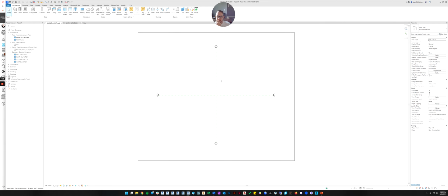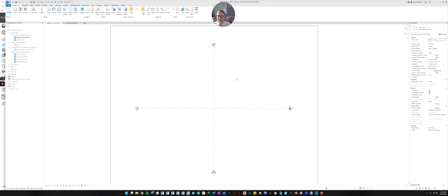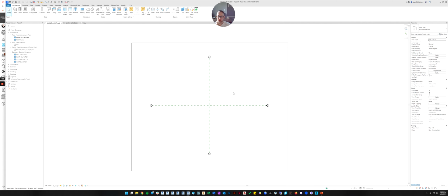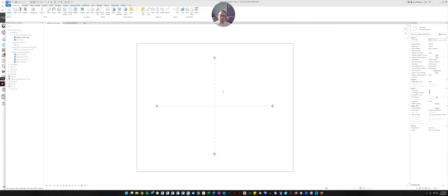So now let's talk about how we start modeling. You know how to model walls, floors, ceilings, roofs. That's great. You've got the fundamentals, but now if you're going to do it off of an existing floor plan, how's the best way to do that? So I'm going to show you how I do it. You could just open up the image file on your iPad or your phone, and you could look from there and try to start building it from there. But I like to bring the image into Revit as a background, and then I can draw on top of it. That's the easiest way I know of.